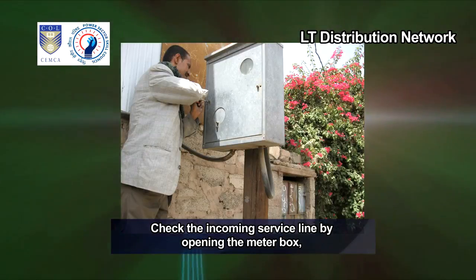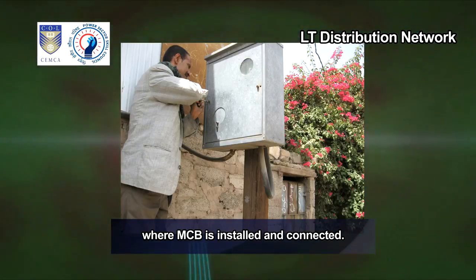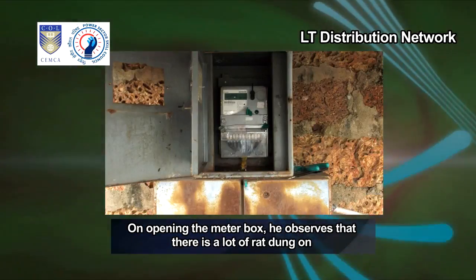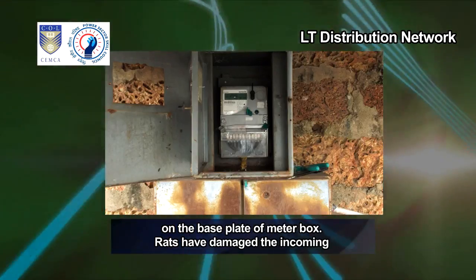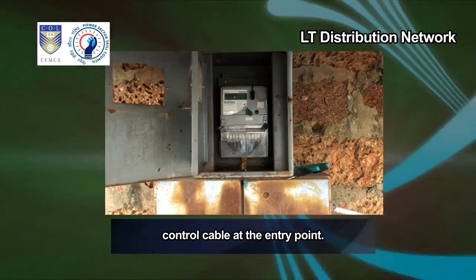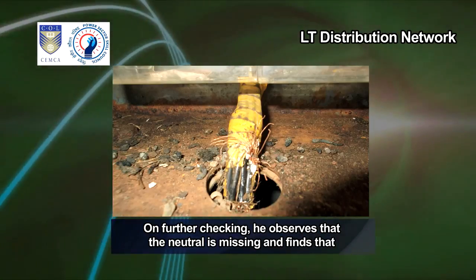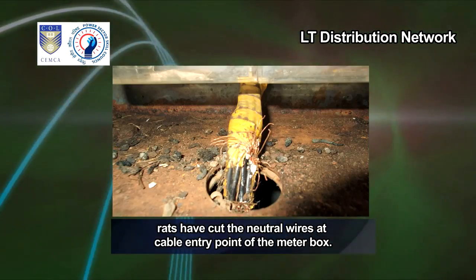Check the incoming service line by opening the meter box, where MCB is installed and connected. He checks the availability of supply at MCB terminals. On opening the meter box, he observes that there is a lot of rat dung on the base plate of meter box. Rats have damaged the incoming control cable at the entry point. On further checking, he observes that the neutral is missing and finds that rats have cut the neutral wires at cable entry point of the meter box.